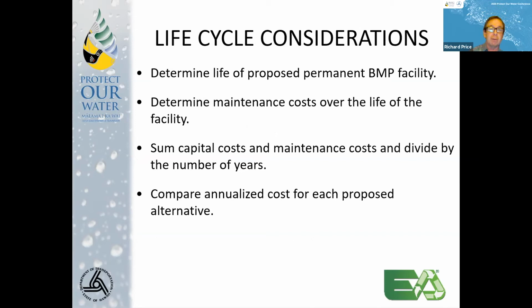And then quickly, I'll touch on life cycle considerations because, again, oftentimes people say that LID can be more expensive, but I think you will find if you look at it over the full life of the device, the maintenance cost can be significantly lower for low impact development, and those annualized costs over time can become very significant. If you have a vault that you're going to bring a vac truck to suck out 2 or 3 or 4 times a year for 20 years, and you start adding those costs onto construction costs, you may find that a rain garden or a bioswale compares very favorably from a cost perspective.